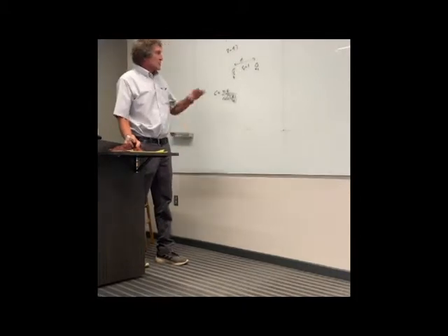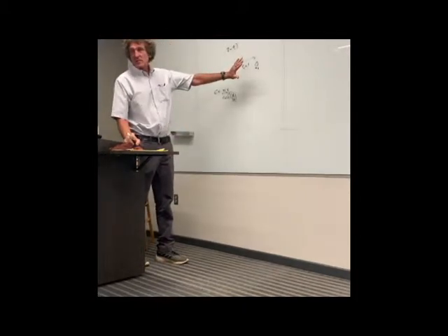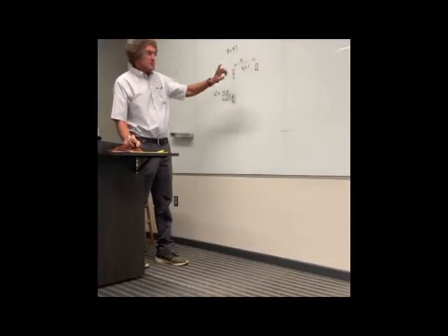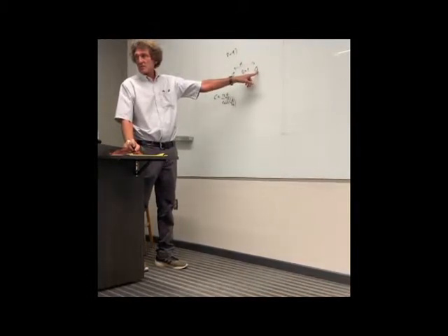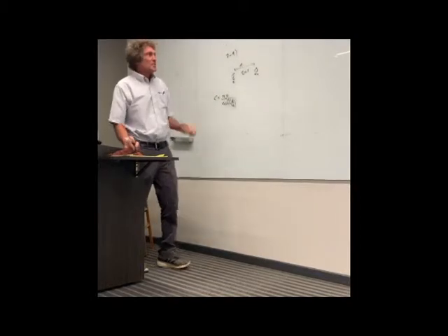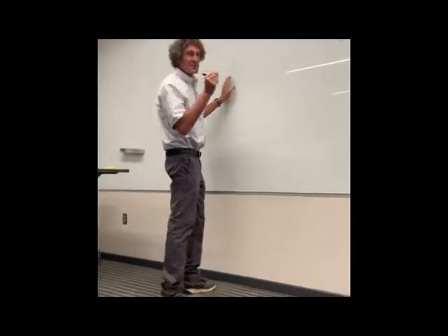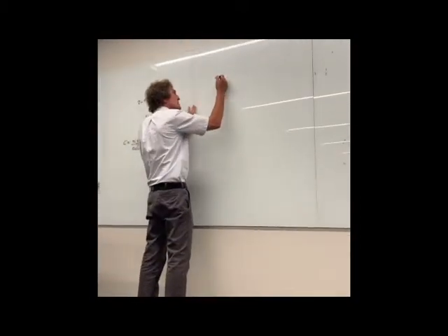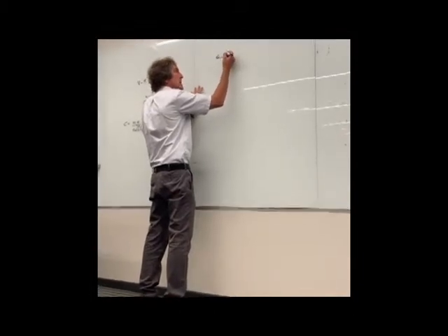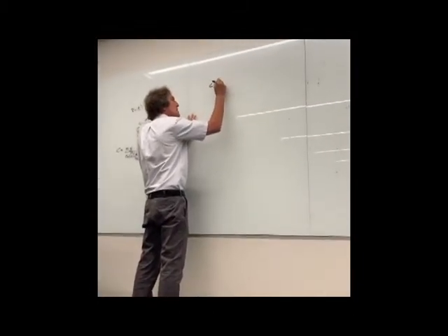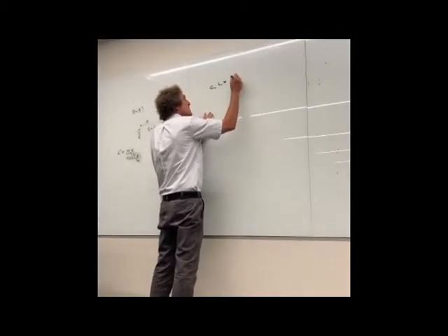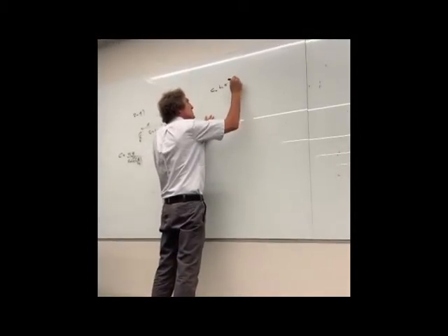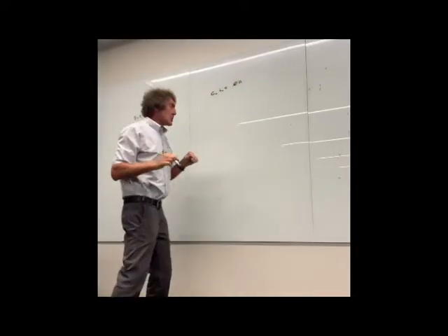Whenever you have a transmission line, do you all agree it's a transmission line? The cross section doesn't vary versus distance. Then there's two conductors separated by a dielectric. Do you all agree with this? So this is a true transmission line. You can use this formula, write it down. I don't know if he has it in his book. You can take the capacitance per unit length times the inductance per unit length, and that's equal to epsilon times mu if the region is homogeneous.